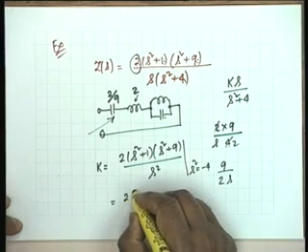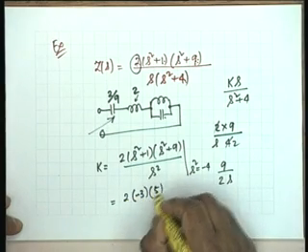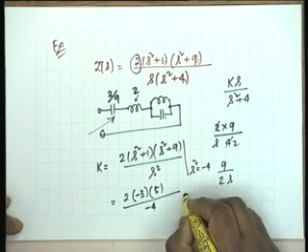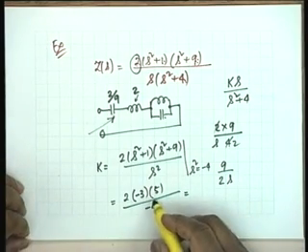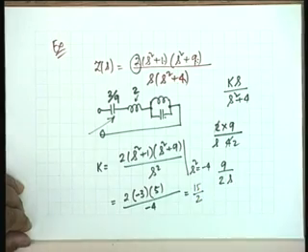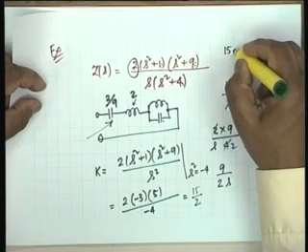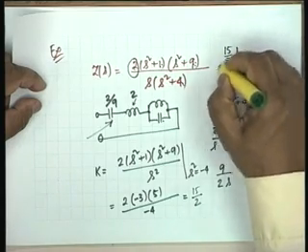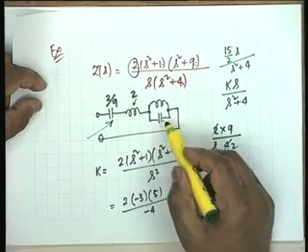So let us do that. 2 minus 3, 5 divided by minus 4. Could this be negative? If you get this as negative, then you suspect that you have done some mischief somewhere. Okay, so this is equal to 15 by 2. In other words, what I get is 15 by 2s divided by s square plus 4, and I can write down the element values now.